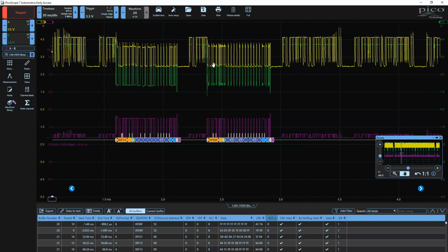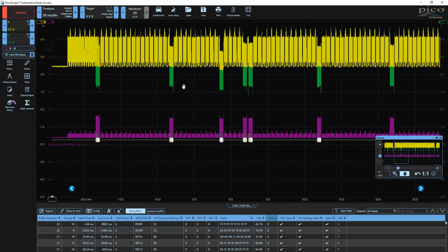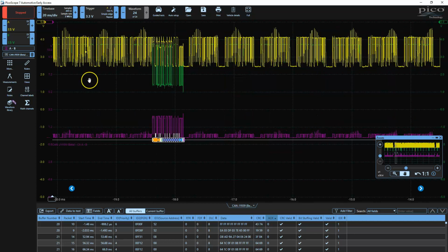More than likely, in this case it's a lift pump, it might be running it at full speed or some speed based on engine load or something. You can imagine it could be anything. I don't know exactly what it's going to be. It's whatever the engineers who designed this system came up with and said, for this failure, this is how we're going to take it. And that failure being, I'm not seeing the fuel pump on CAN.